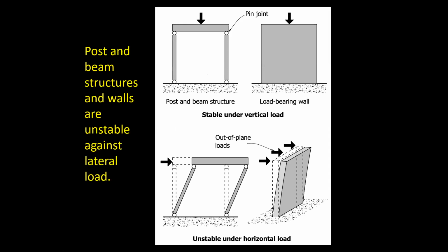Then when it comes to wide span structures, we still have to remember that if we have a post and beam structure, it is unstable for horizontal and earthquake loads. And even walls of a long span structure are unstable for loads at right angles to the length of the wall.